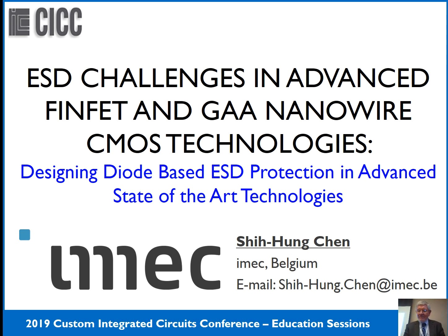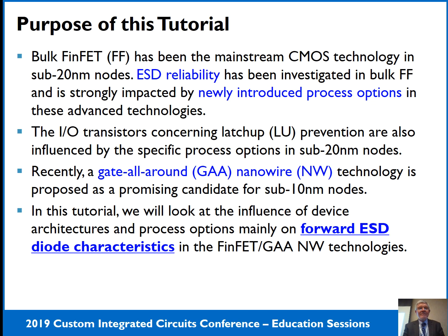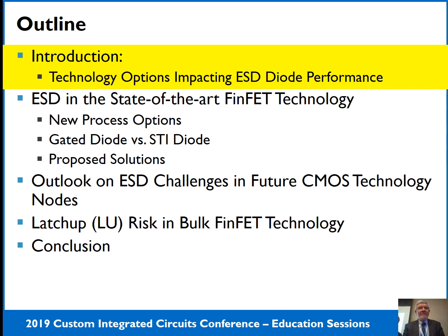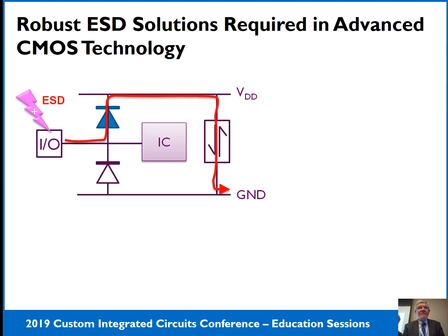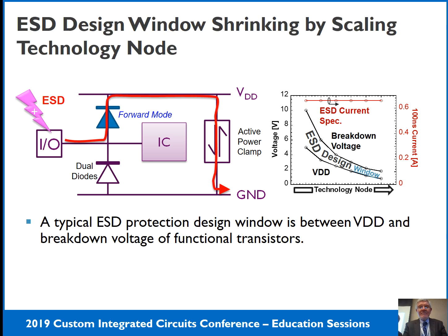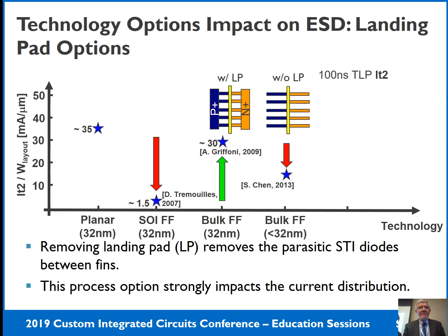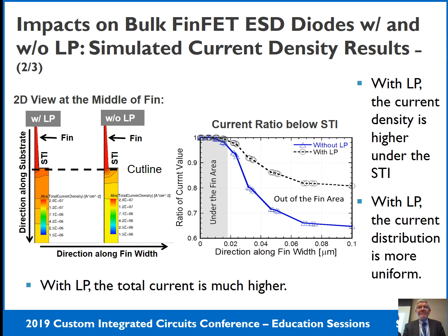I think if this is a diamond shape, your question is why we use such a diamond-shaped epitaxial? Because this can increase the contact area. So can we not grow a square? That will also increase the area. But because it's epitaxial, you need to follow the crystal orientation, right? Okay, so it's because of the crystal. Yes.